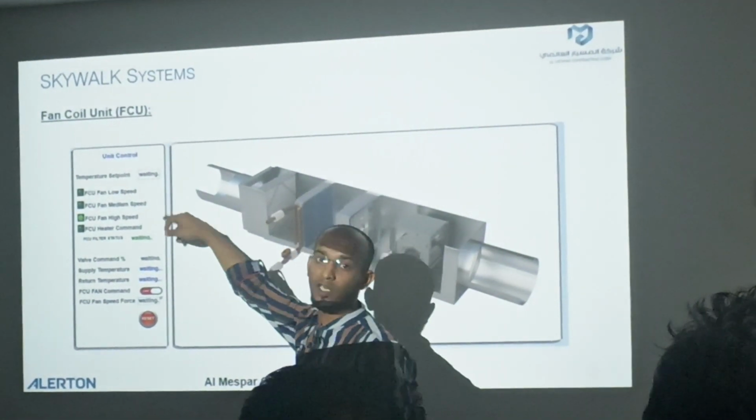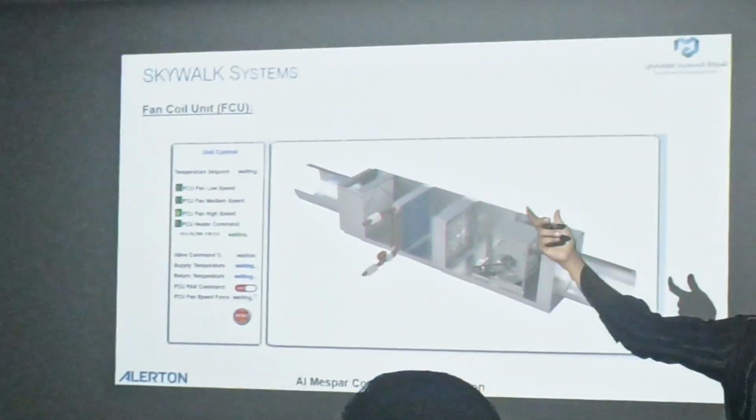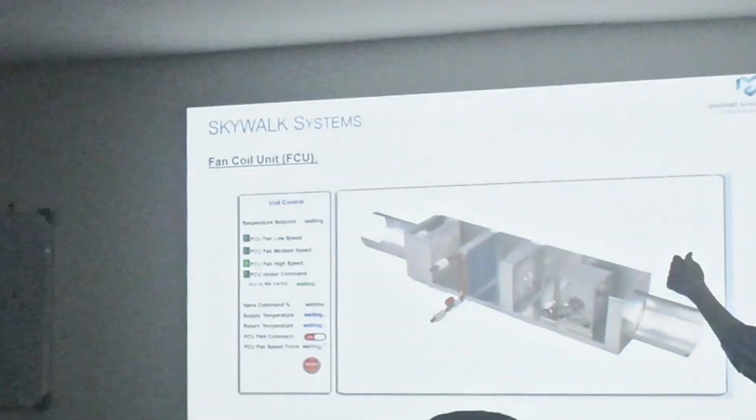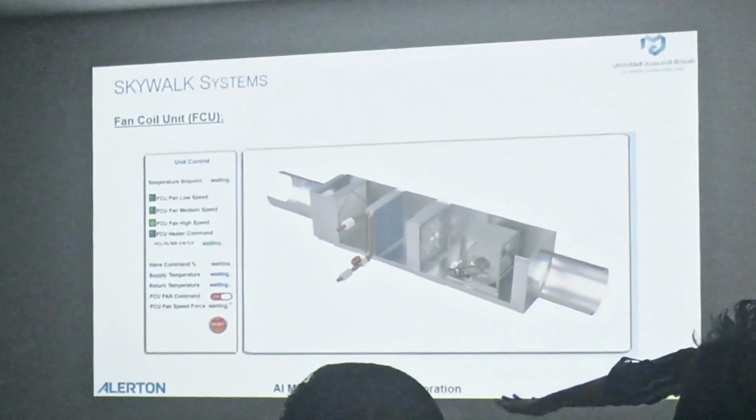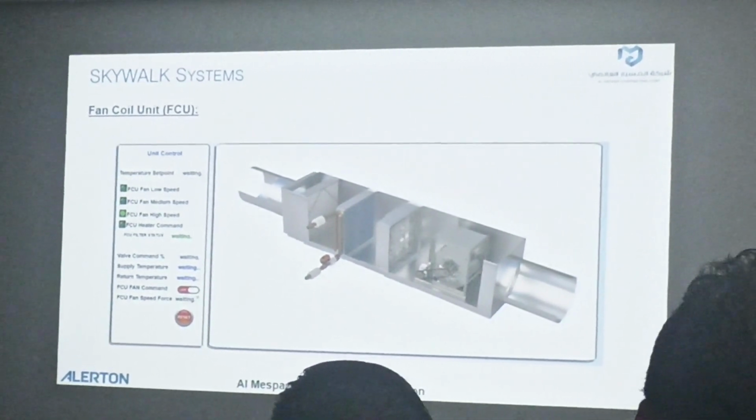If the difference is more than 3 degrees Celsius, and the set point is higher than the return temperature, the heater will get activated and the valve actuator will. There is percentage for the cooling valve, like 50% open, but not for the heater.